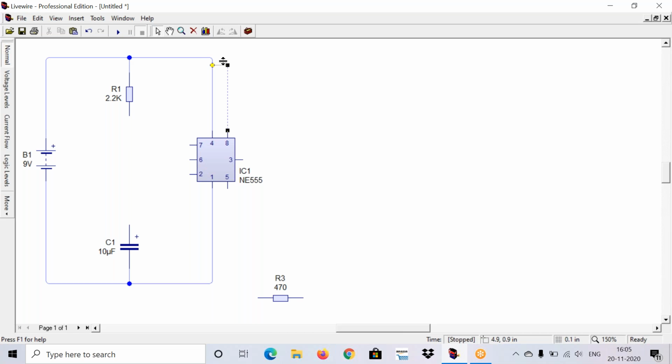After that, you need 2 resistors in the circuit. You can directly copy and paste the resistors available to you. Next, from the discrete semiconductors take an NPN transistor, and from the input components, you need to take a DPDT switch. We need a switch for changing the rotation. These are the components which are required.